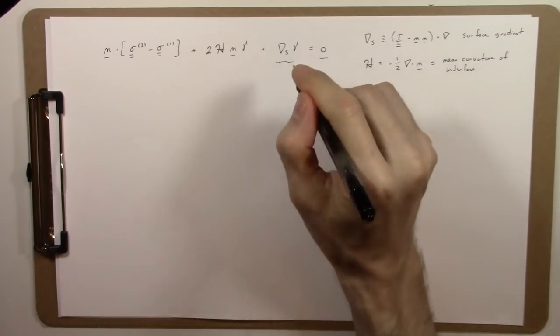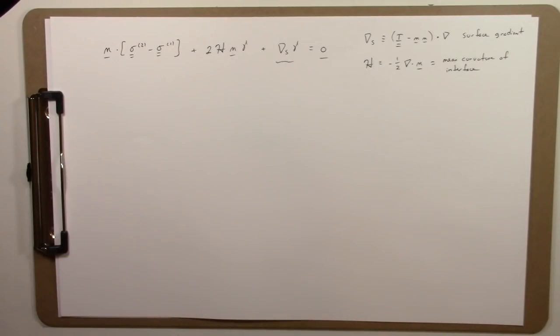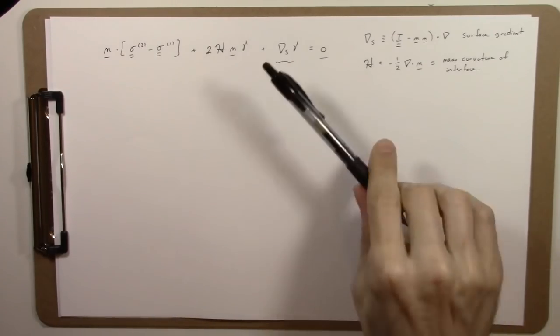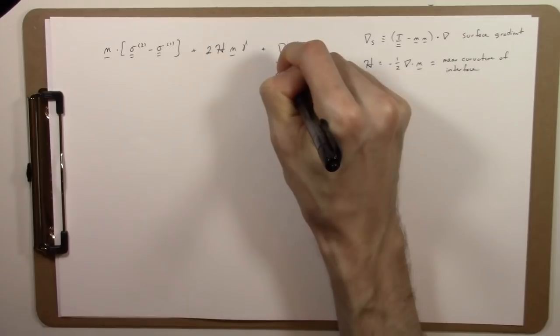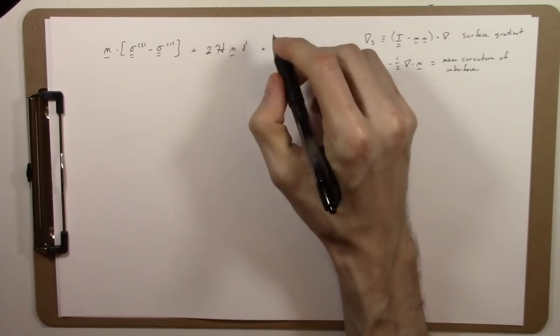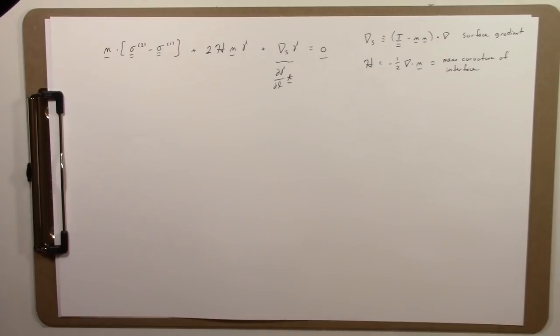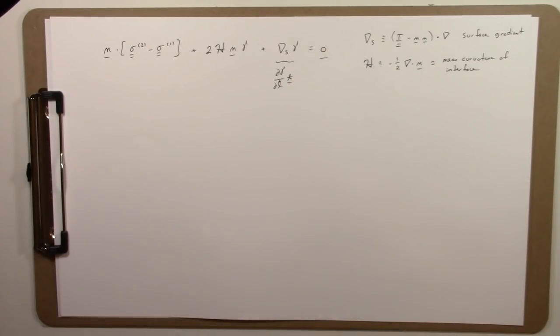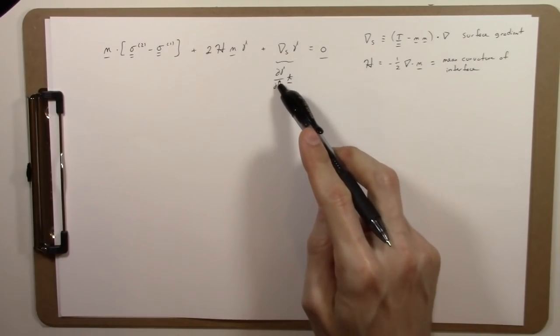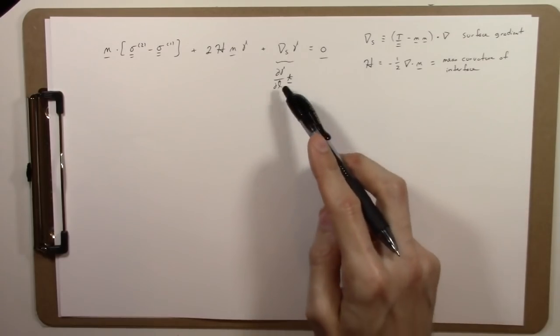And this term here, del_s gamma, is essentially the gradient of the surface tension in the plane of the interface, and that can be written as d gamma dL, where L is arc length, multiplied by the unit tangent vector t. So t will be the unit tangent vector pointing in the direction of the most rapidly changing interfacial tension gamma, and this L hat term will be the arc length in the direction of the unit tangent vector t. So this then will be the rate of change of the interfacial tension with arc length in the tangent direction in which it's changing most rapidly.